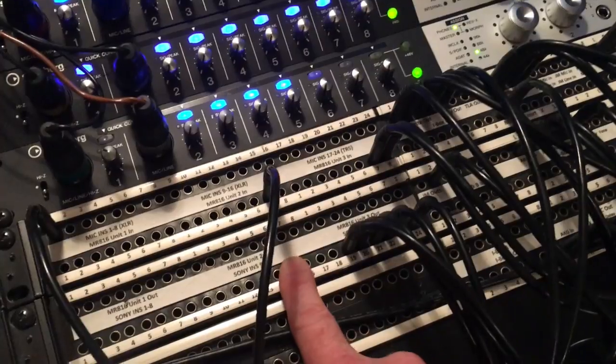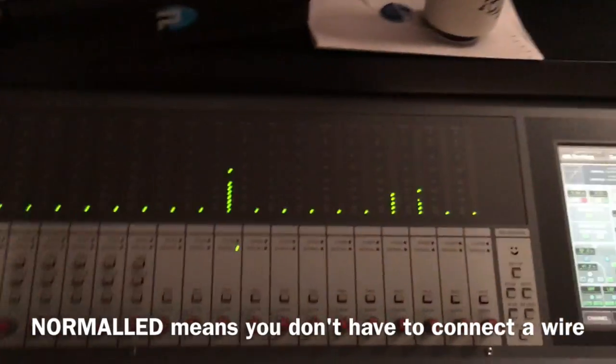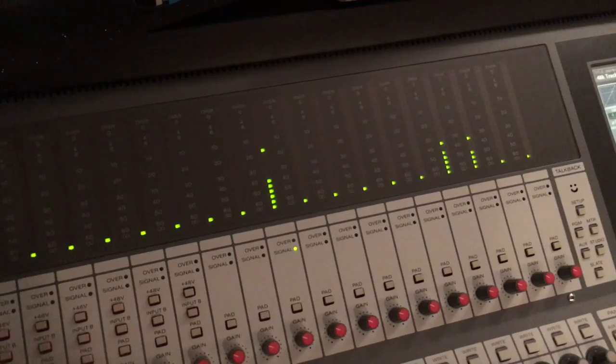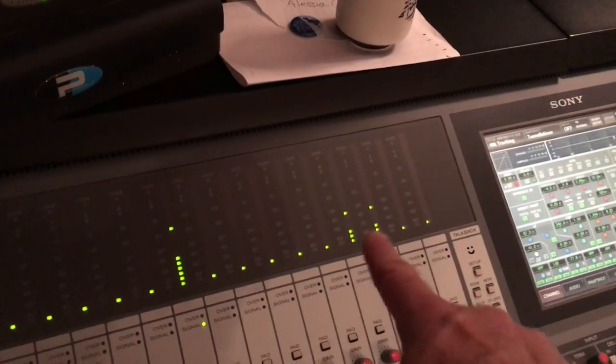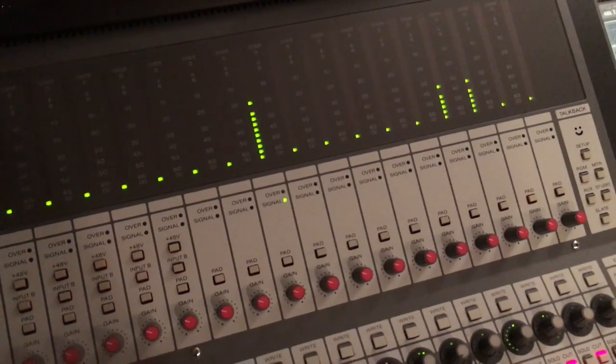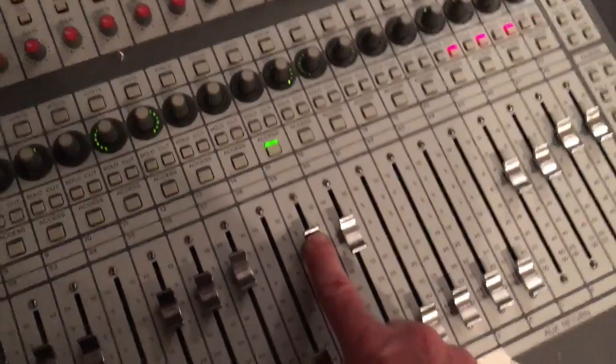So once it comes out of output number 15 on the patch bay, it's automatically normaled, it's called, or wired straight into channel 15 on my mixing board. So when I talk, you can see that meter moving. I've got a little reverb coming back there. So that's how I can now get that channel individually on a channel fader on my mixing board.